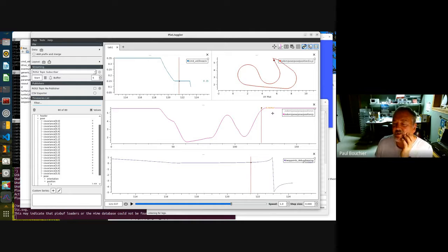So it's getting pretty close. It's getting within the acceptable error range of the 5.5 target. And the bearing to the waypoint is pretty close to 0, but it's about to increase sharply as it comes alongside the waypoint.